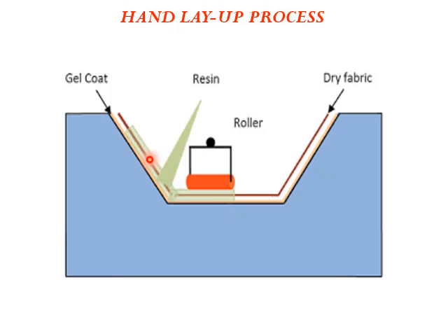Many times, once the gel coat is applied on the mold surface, they directly place the fabrics, that is the reinforcement, on the gel coat, then pour the resin directly over the reinforcement material. You can have it in that way also, or in this way. Having a layer of resin below and above will ensure proper wetting of the fabric material, that is the reinforcement material, by the matrix or the resin.